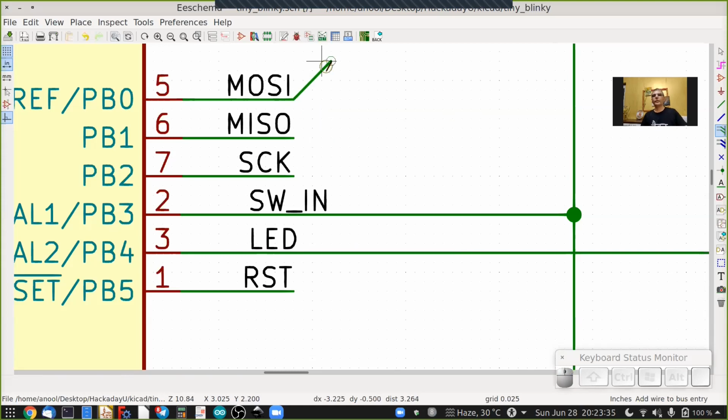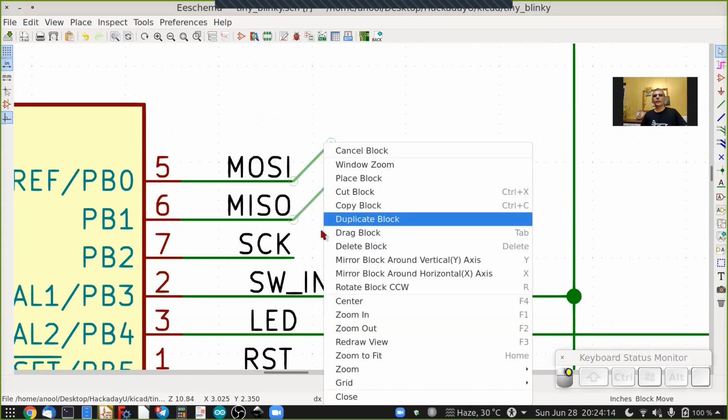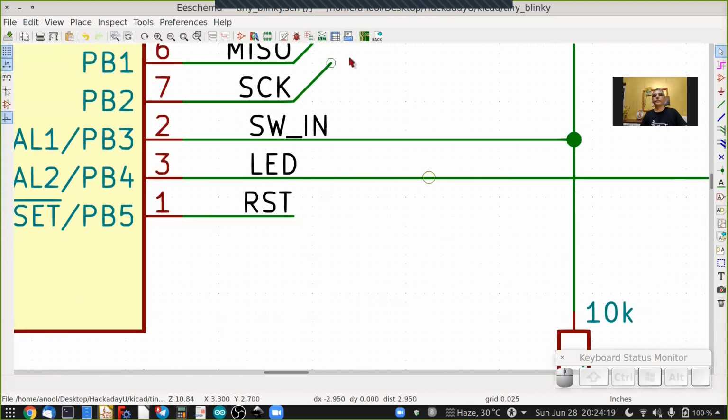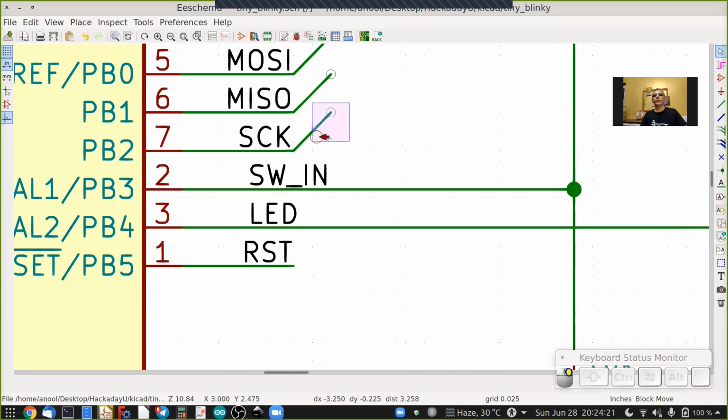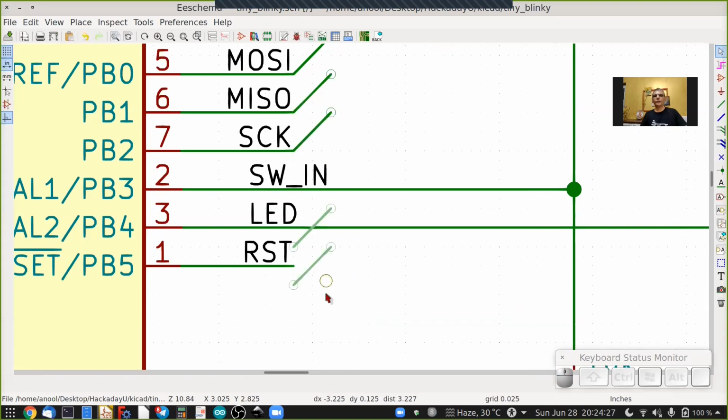And now to make things easy, we can just right click and duplicate and do it there. Do it again, draw a block, right click, duplicate, keep it here. Then repeat it one more time for the fourth one. Right click, duplicate. Grab two, but it's okay. I can take one and delete this one. And then I need to change the orientation. Right click, first wire entry, set this, and we actually have two of them over here, so delete the other one.